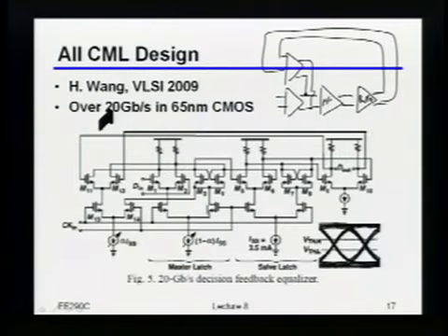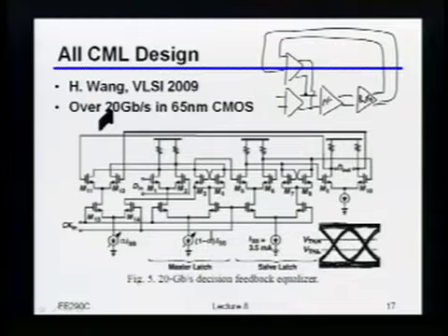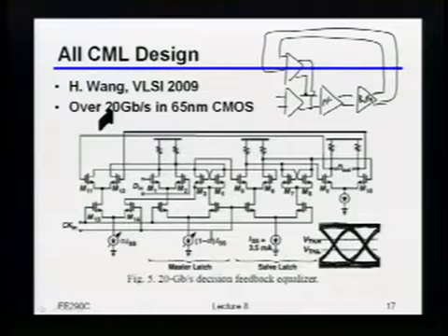I think the equalizer itself, just this piece by itself, and actually maybe we can even figure it out because they gave us nicely enough in one place the bias currents. But I think this whole thing was maybe on the order of 20-ish milliwatts or so, somewhere in that ballpark. And by the way, you can work out exactly what the numbers should be just based on the design equations we went through. But it's in that ballpark.